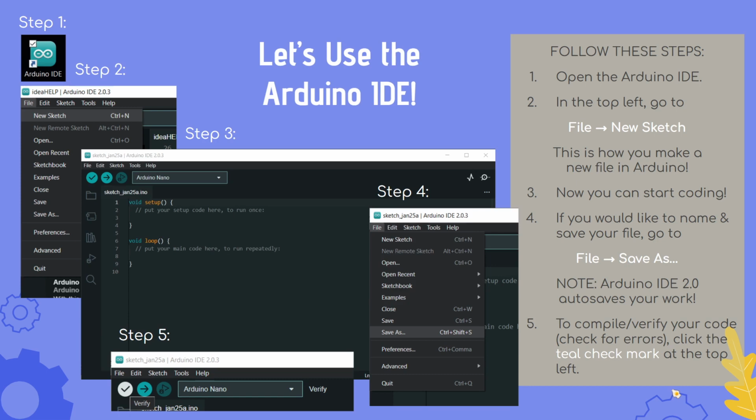So first things first, you open Arduino IDE. I hope you've already done that, but then the next thing that you're going to want to do is make a new sketch because we're going to make a new project. We're going to make a new file. To do that, you can just go to File and click New Sketch. That is to just open something new. If you're opening the Arduino IDE for the first time, you're probably already going to have some kind of empty sketch in front of you, and you can use that if you want, but I just wanted to make sure to include this in case you want to make something new, so you know where you can make a new sketch.